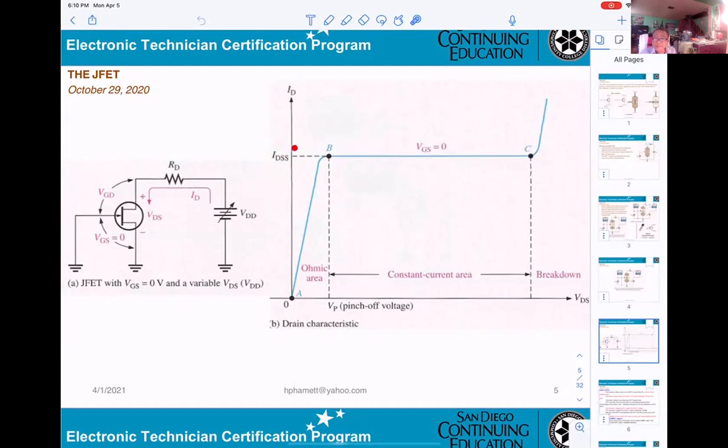That means the maximum current, okay? And then after that point, the current will be constant, no changing. That will be at VGS equal 0. That means VGS equal 0, then the current ID will be equal to the maximum current. They call it IDSS.